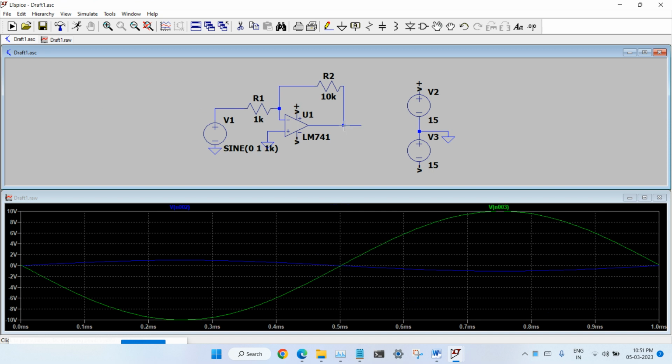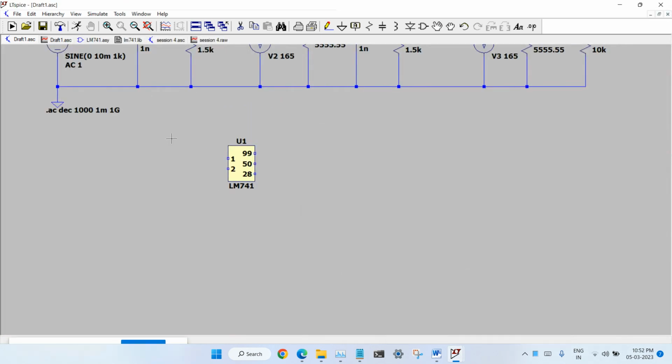Now we can look at the output wave. Here we can see that it is minus 10. The maximum amplitude we get is 10 volt, but as the 1 volt amplitude sine wave goes up, this sine wave goes down. That is the 180-degree phase shift, which happens because of minus R2 by R1. If you don't know, you will study it when you learn about op amps. It's the inverting configuration of an op amp. If you are curious, you can just search the web for it. So we get the result as expected. So that's all. I guess we have covered everything.